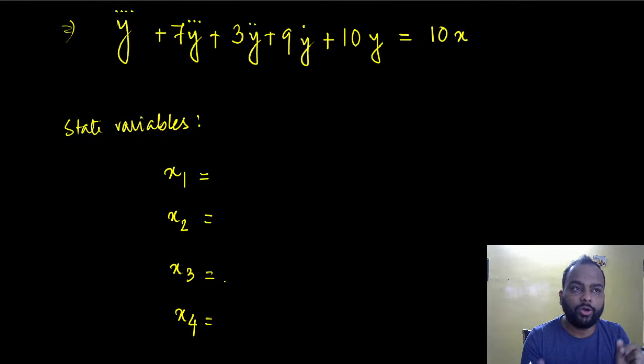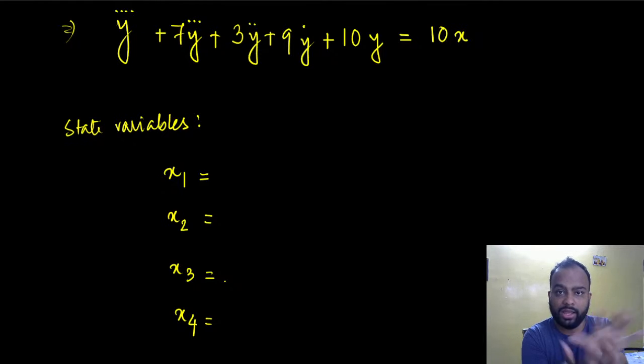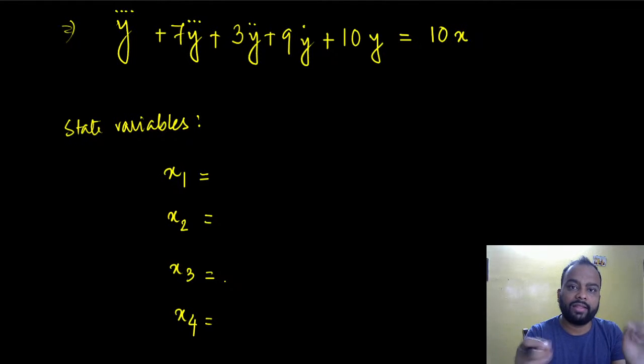If I want to design an observer, and what an observer is we shall learn later on, then we shall convert the state space model into another suitable state space model in which designing an observer becomes easier. The point being, since we have infinitely many different representations for the same system, we can at our will convert the state space model into another equivalent state space model that is suitable for designing a controller, maybe designing an observer, maybe doing some other things with it.